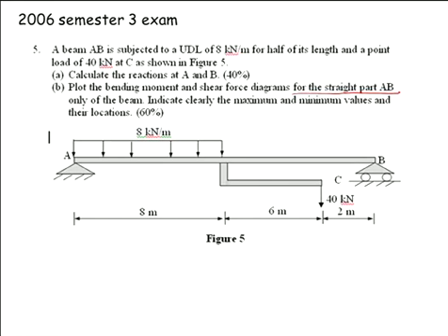Okay, there is a little bit of a trick here. Without that, you could still calculate your reactions. Reactions, force times distance when you're taking moments. So if you were taking moments at A here, you would put an equivalent point load on here, you would say I have 40 kilonewtons acting here, and you could calculate your reactions.